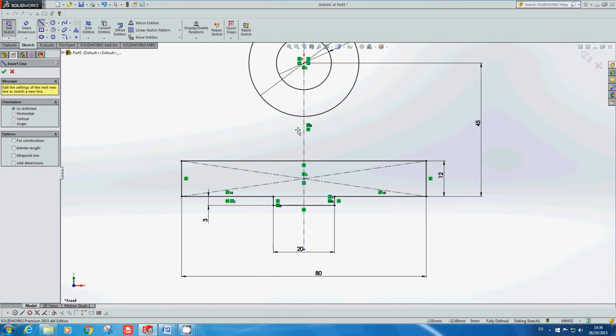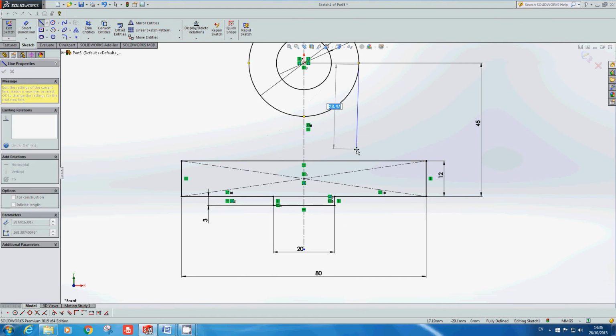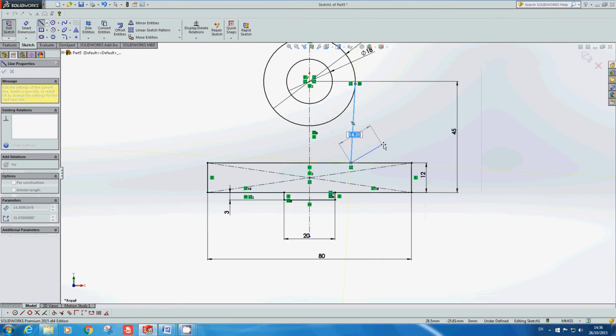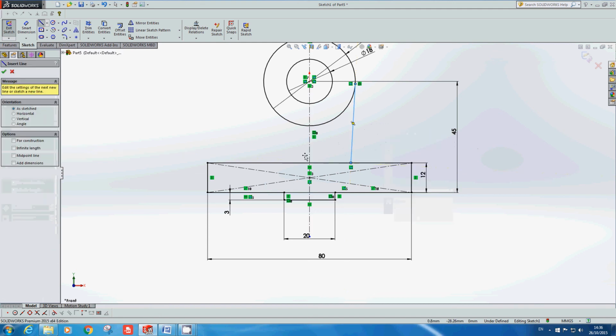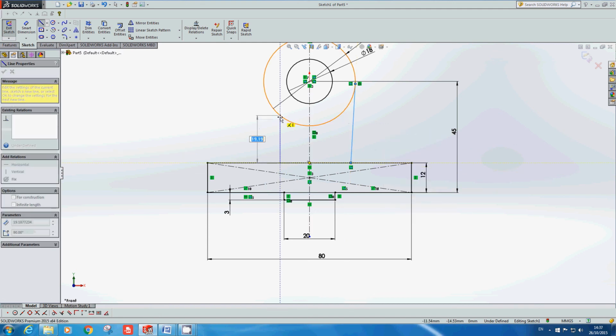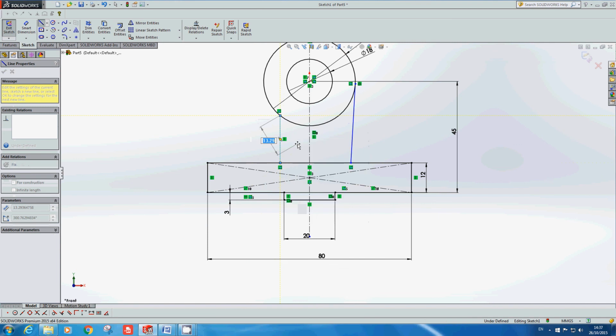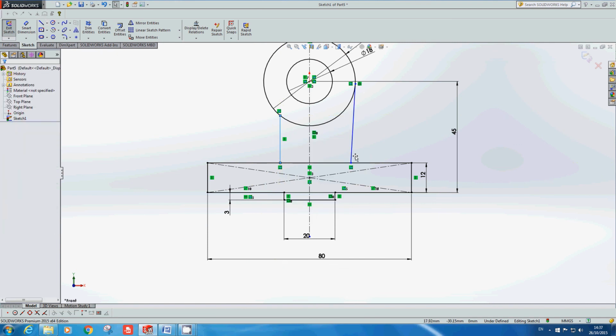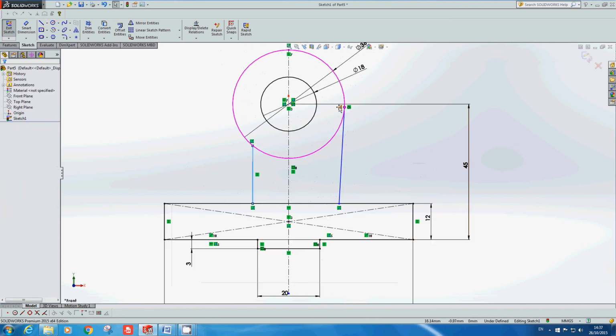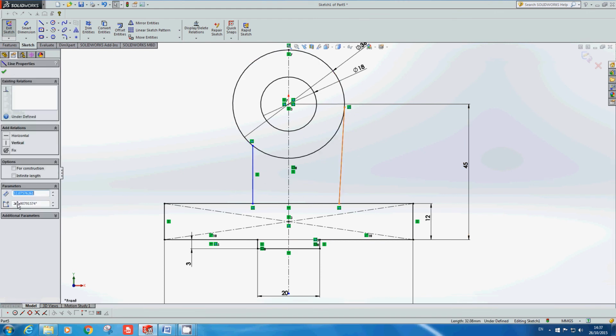Again, I'm just going to use my lines. So let's snap that dreaded tangent constraint again. I'll delete it after. If I start from the rectangle up, that won't happen. So trace up, coincident is fine, tangent, remove, click it, delete it. Click the line again, then come across here and click vertical. Let's pull it in a bit.